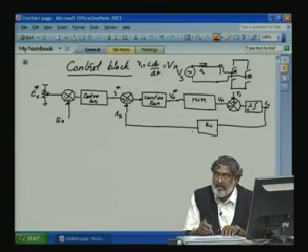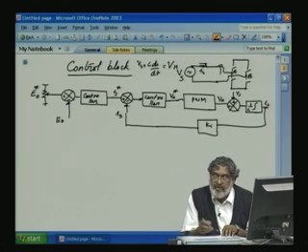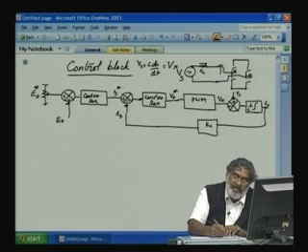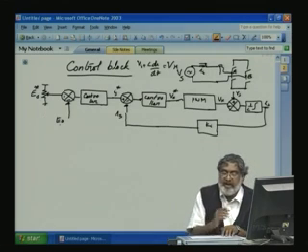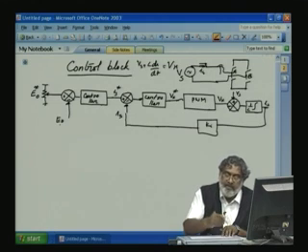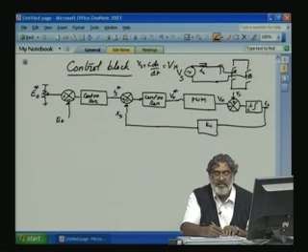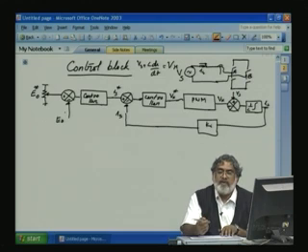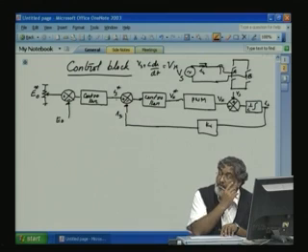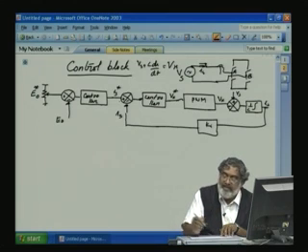Now, this is an inner current loop. Here, again I will explain, you have the E0 reference and feedback we are taking from the converter. If there is any mismatch in E0, it reflects on the type of load current required. If there is a variation in the load current, that should reflect on the input current drawn, Is. So, this controller output should point to the Is star. This Is star and the actual current Is we will compare, and this comparison output will go to a controller.